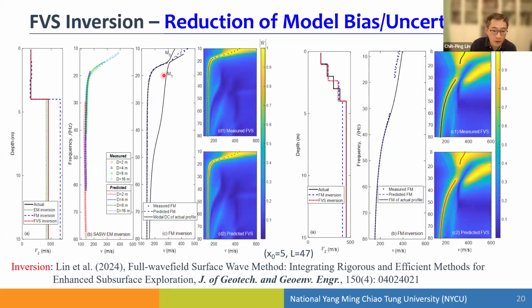But if you perform it like in MASW, a lot of people are using fundamental mode inversion. So this is the case where there's a mode kissing. You cannot notice this because there is no theoretical dispersion curve behind it. And if we interpret this as a single fundamental mode, you get a large overestimation of the velocity of the lower half space. And this is another case where you have a high gradient.